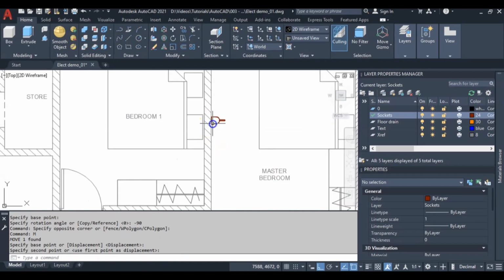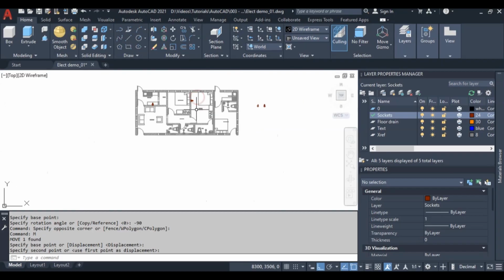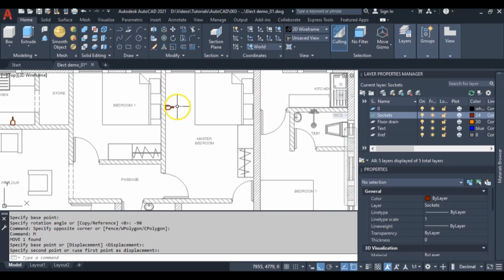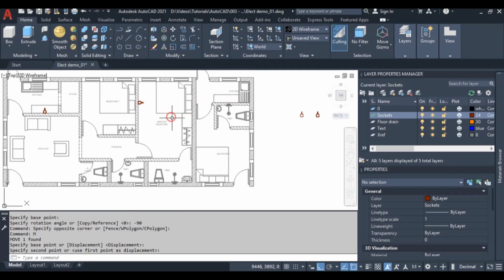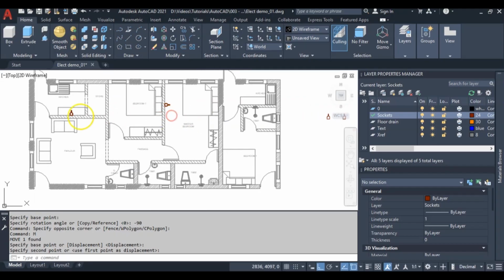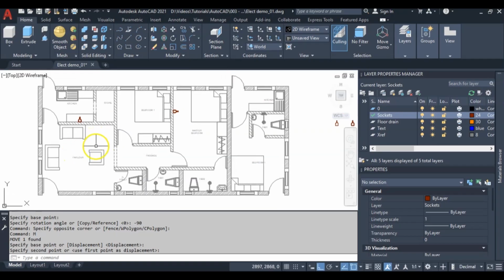Just anywhere really. So zoom out, you can see it's looking predominant on your XREF building plan, and it's easy for the installers or whoever is going to make use of this drawing to see your normal sockets points and also install accordingly. Thanks.